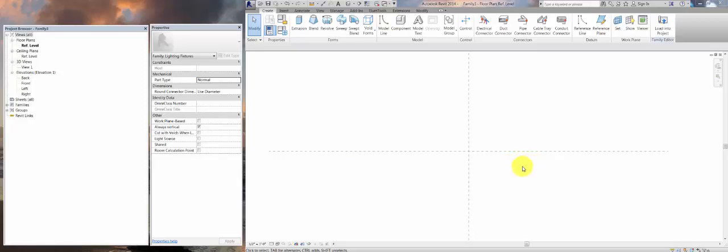Normally, you don't add an electrical connector until you make the 3D shape, but if you're creating a file that you want to use as something to save as each time you make a new fixture, you may want to have the electrical connector already set up. Or maybe you would like to make a fixture that actually has no 3D content and just acts like it does. So we will be starting out making a family with an electrical connector and a symbol, and finally making the 3D content at the very end.